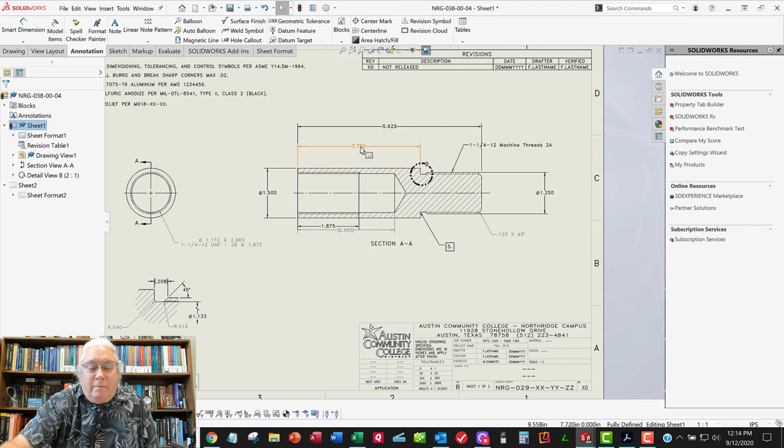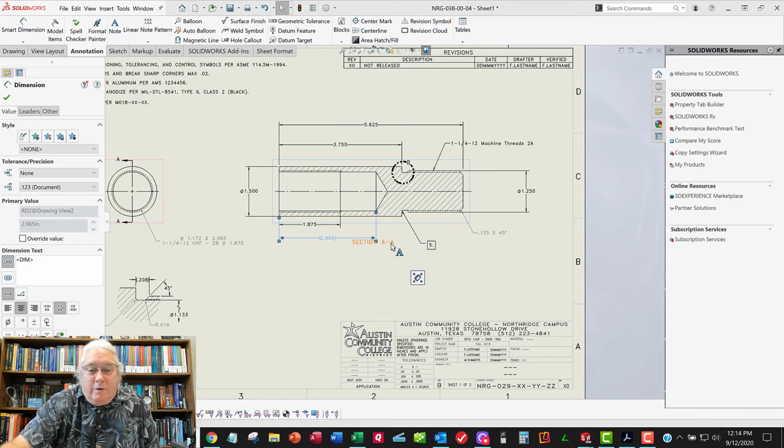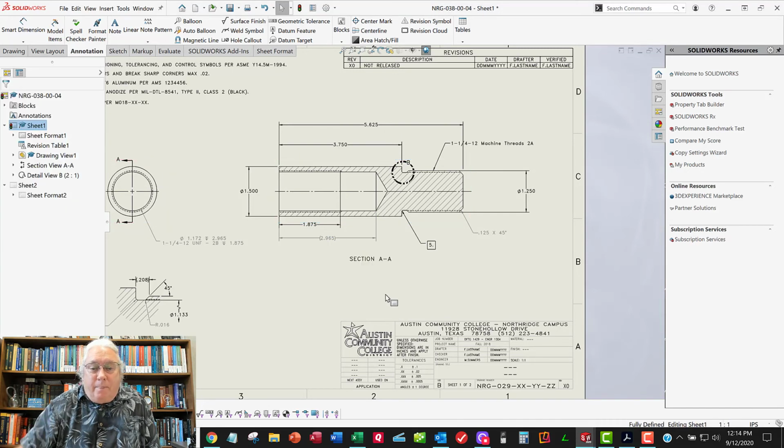But this one here, maybe this one is going to be the height of this thing sticking off the plate. I really care about that one, so I'm going to leave that one at 3 decimal places. And I want you to decide these other ones whether they need to be 2-place or 3-place dimensions. All right, so other than cleaning these dimensions up and maybe throwing an ISO view on here and doing your title block and your revision history and your notes at the top, maybe we've covered everything. We've covered enough stuff anyway.